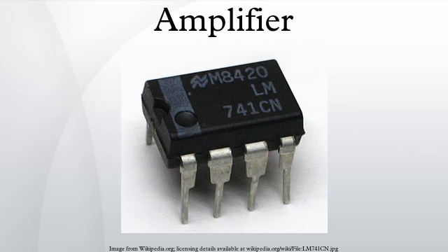The Class Ef amplifier is a highly efficient switching power amplifier, typically used at such high frequencies that the switching time becomes comparable to the duty time. As said in the Class D amplifier, the transistor is connected via a serial LC circuit to the load, and connected via a large L to the supply voltage.